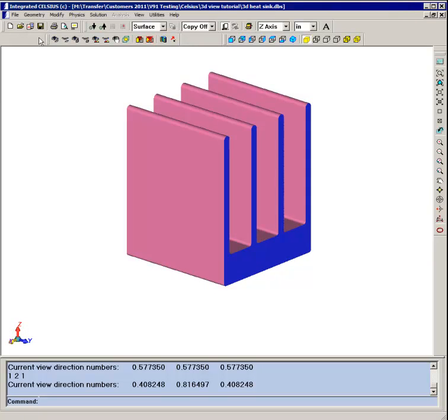And the last toolbar button, which is very useful when you're working in 3D, is the visibility toolbar. One of the key challenges in working with a 3D model is being able to isolate parts that you need to work on, because different parts of your model will need different boundary conditions or materials, and in a 3D model that becomes a challenge. In 2D everything is just laid out on a plane for you. It's easy to pick different regions.